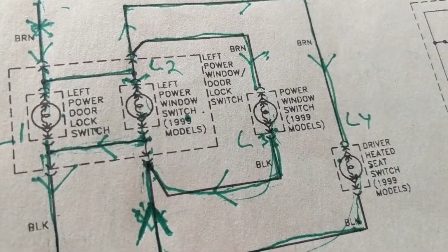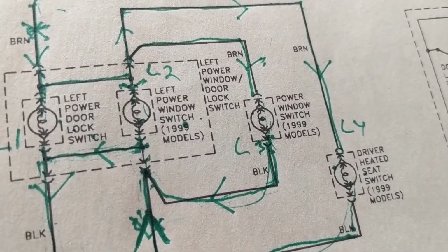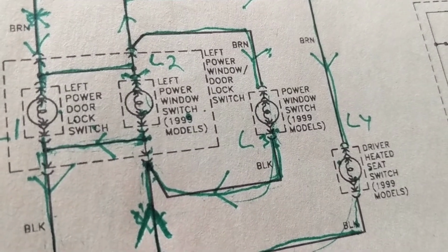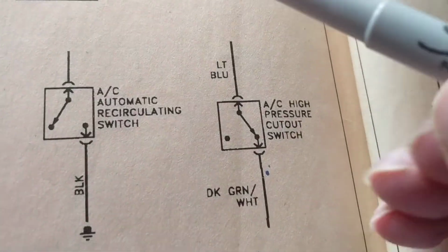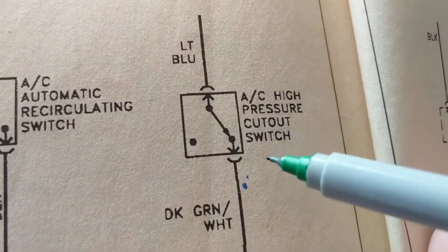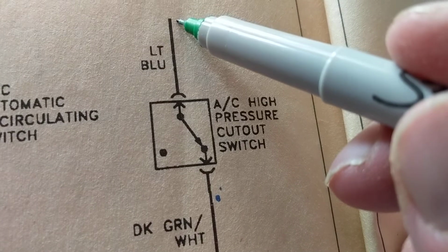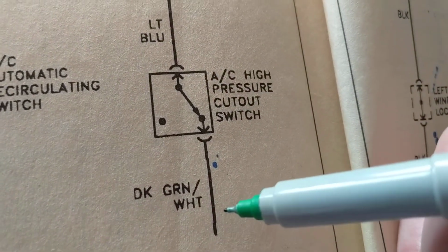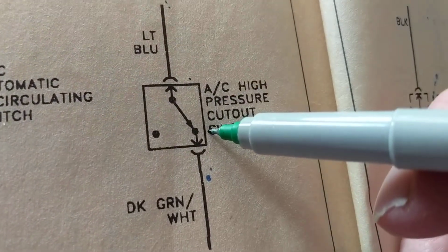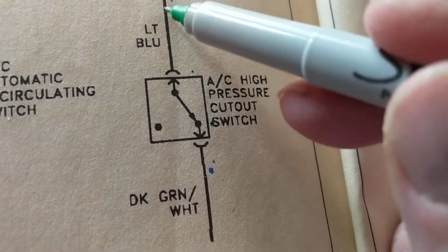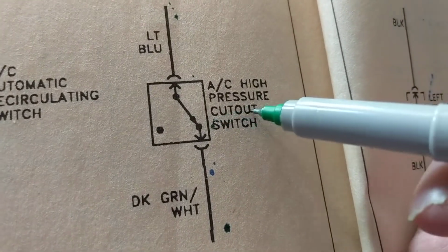Let's take another one, a relay, which somebody gave many comments on how the relay works. It is a very difficult subject, but let's continue with that one. Okay, before getting to the relay, the AC high pressure cutout switch. So one side is an input, the other side is an output, telling the computer AC high pressure cutoff switch. This is in the rest position. This is telling it that it is connected. This point is connected to this point. That's the rest position.